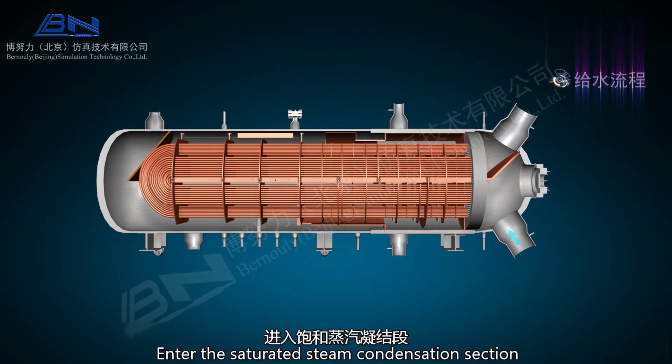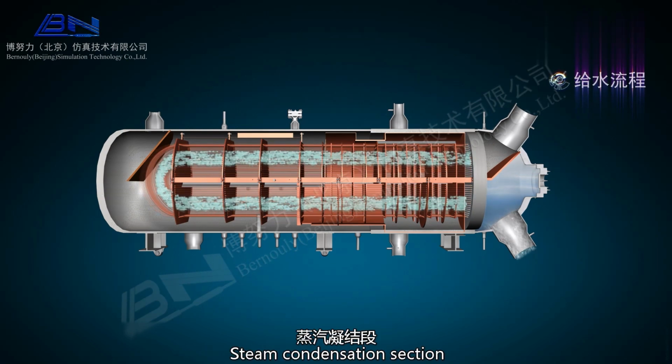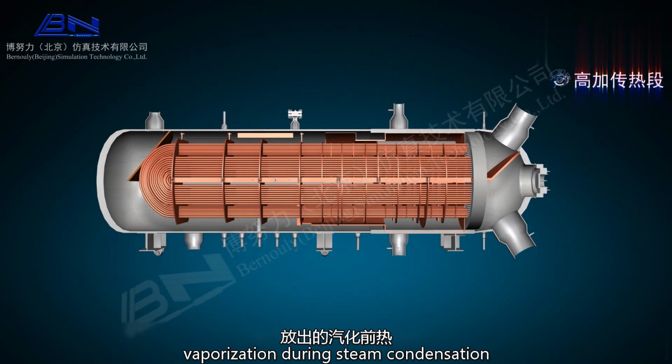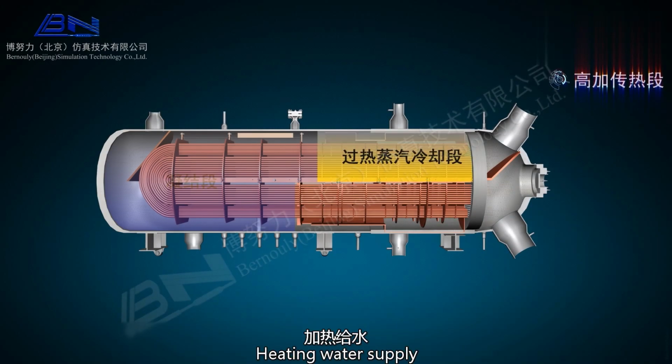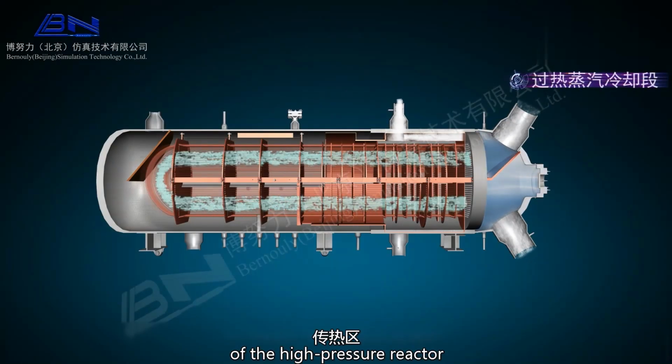It then enters the saturated steam condensation section, exchanging heat with the water supply. The steam condensation section is where the heat is released, as the latent heat of vaporization during steam condensation heats the water supply. It is the main heat transfer area of the high-pressure heater.